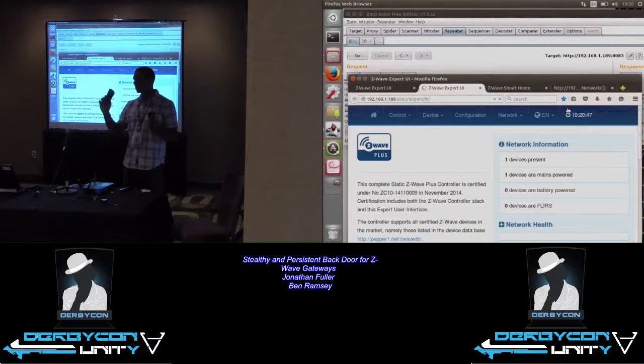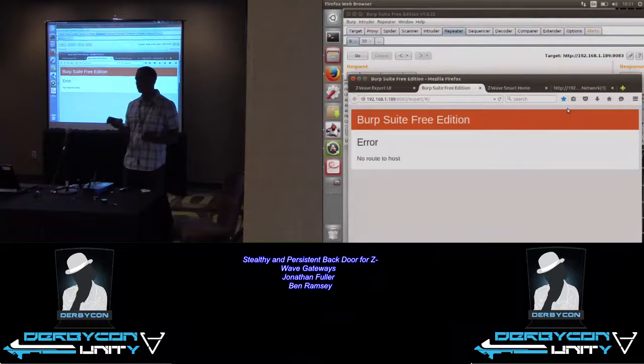And the cool thing about these, this could be your ZWave network. So you can just bring one of these home and add individual devices. Obviously, you only have local access to your device, or up to 20 meters. ZWave says, I think 100 meters, but it doesn't really go that far, at least in my experience. But yeah, you can just add devices to your portable controller and have local access only.